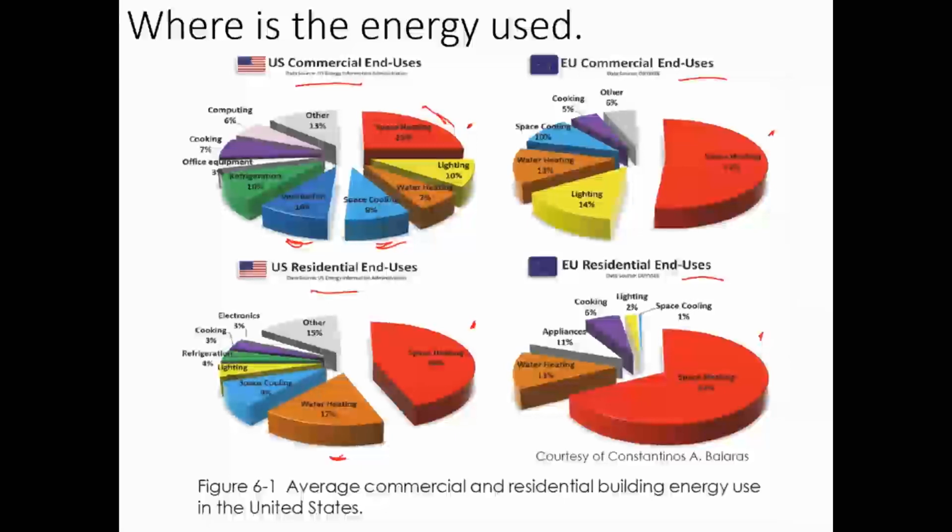In the summer, it adds to your cooling load, right? You're putting heat into the space, an additional heat load, so you're going to have to work harder to cool that space. So there's a trade-off when you switch to LEDs, but the savings are definitely worth it. But again, we're always thinking about our buildings as a system, right?